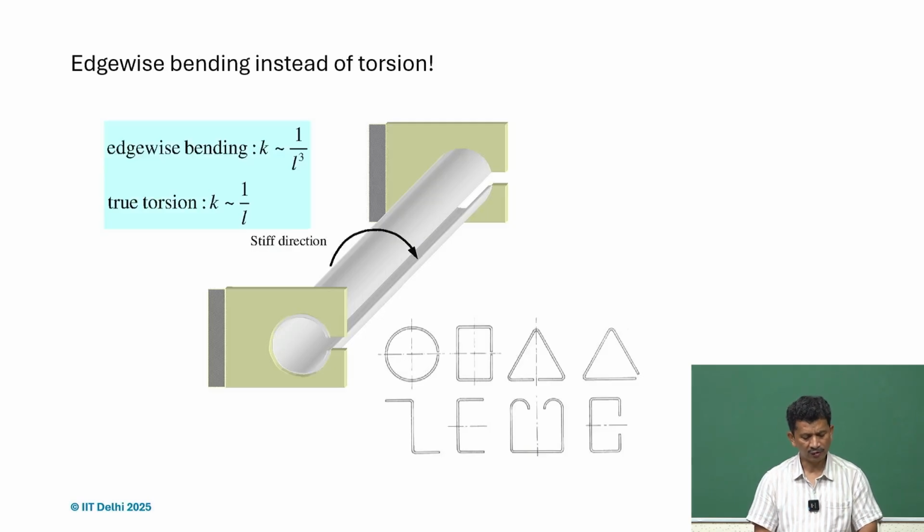So what we also have to understand is that even if it's an open profile, if we seize the relative motion either by locking along the seam or locking the movement at the ends, many times we can achieve the stiffness of the closed sections. And many times we want these open sections because of the ease of manufacturing, the ease of production of these kinds of sheets.